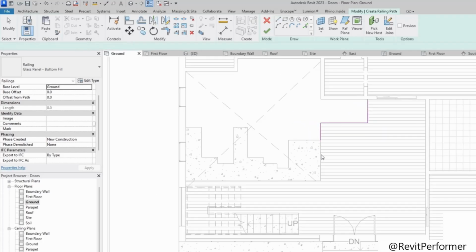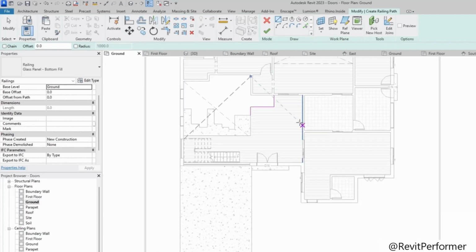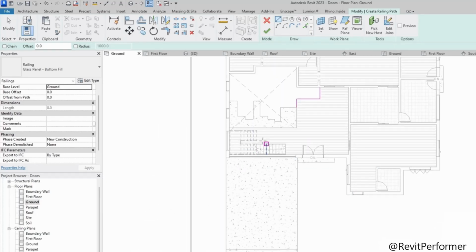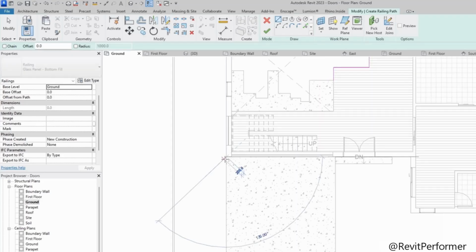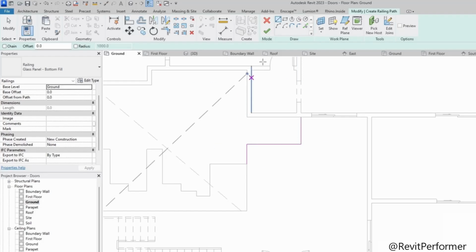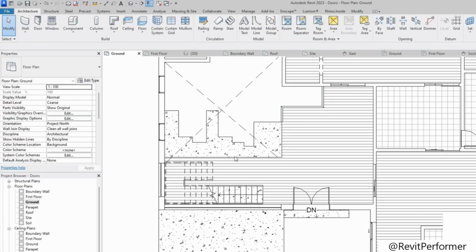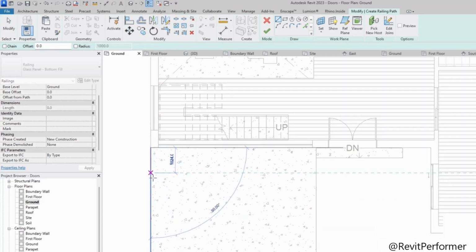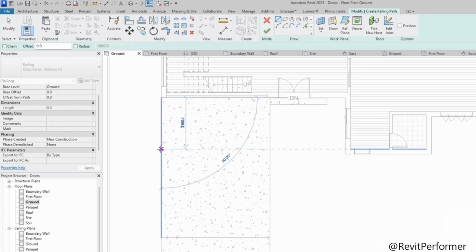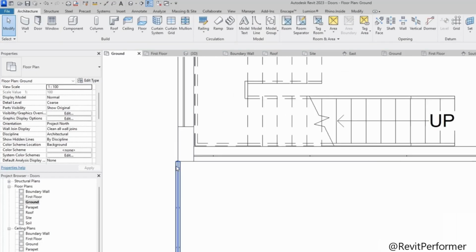So this is the only place where I'm going to place a railing on the ground floor. There's not much required where we need it. Oh, sorry, we can't place it. Oh, yes, we can. But in a single sketch, you need all the lines to be aligned. So, all right, do that now. Go to railing again and sketch them. Like I want up to here. Railings there as well. Okay, great. So we have railing over here.